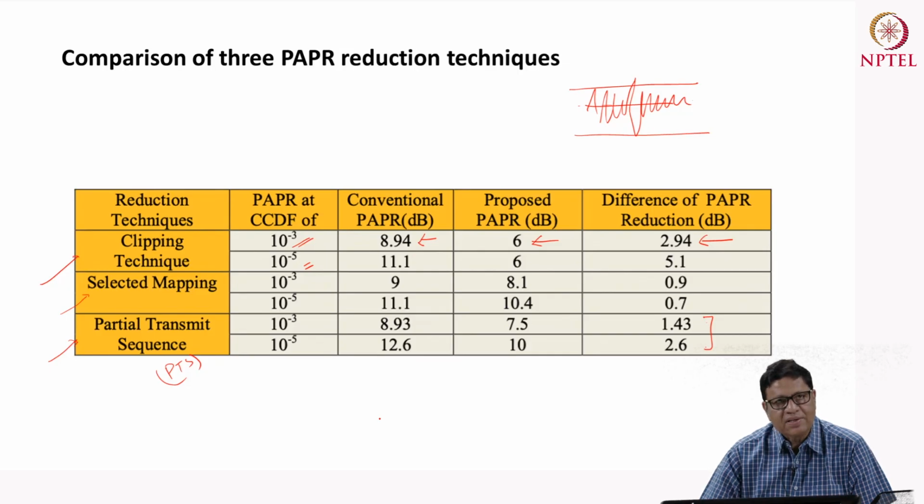After that we discussed what happens if there is a frequency offset of the subcarrier frequency, how the SINR degrades, and then we also understood PAPR, which is the main issue in OFDM transmission, the effect it has on the performance, and what the different PAPR techniques are.